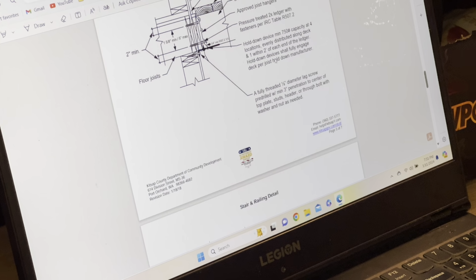Another page for your handrails. Pretty basic stuff, right? 6-inch diameter, that's usually right here at your treads. 4-inch diameter in between your balusters. And ours, I guess, says for your stair balusters, you can be up to 4 3/8. It tells you your handrail heights. And then it gives you a little sketch if you want to do a site plan on here, included with the scale for their grid.